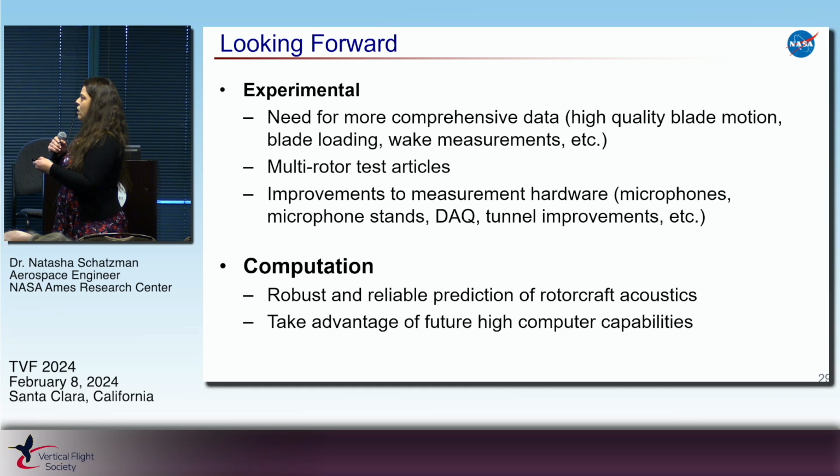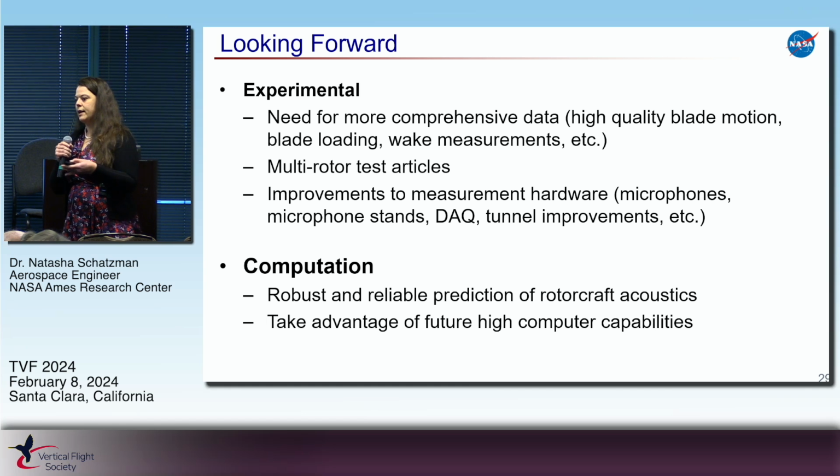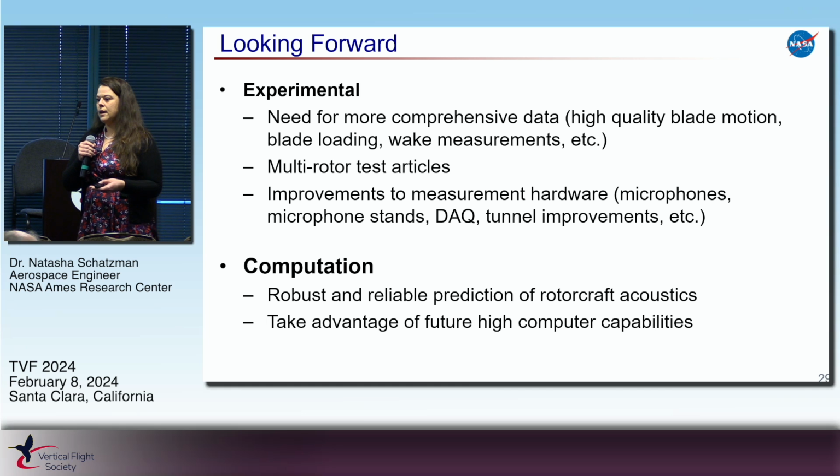This doesn't only include microphones, microphone stands, or DAQs, but also tunnel improvements. As we design rotors that become quieter and quieter, the background noise needs to also come down so we can get a good signal to noise ratio and really see how loud that rotorcraft is. So improvements to tunnels is very critical if we want to continue to progress forward.